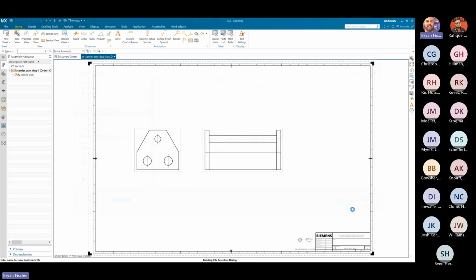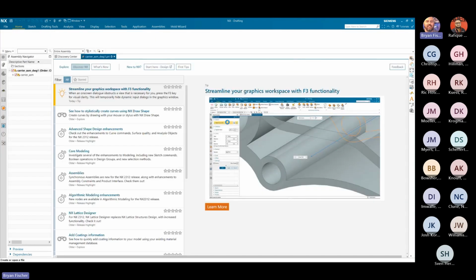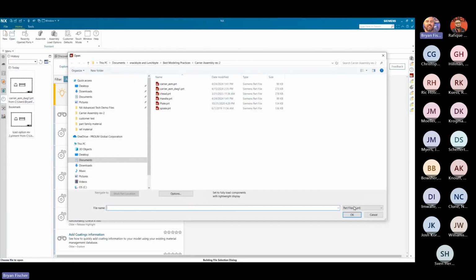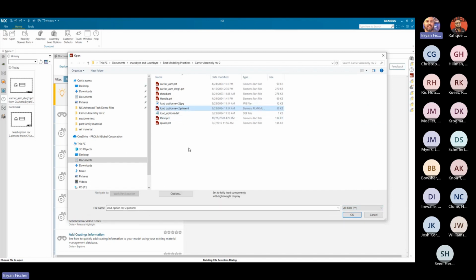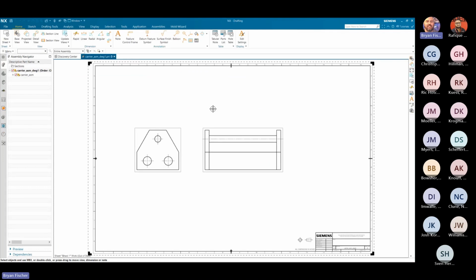I'm going to say OK, and close this again. This time when I come to open it, I go to File Open, and if I take this down to all files, I'm going to get a .plm XML file. If I hit that, it's going to load all my options and everything and open my file up. So that's a great way to bookmark and have somebody just be able to go in there.